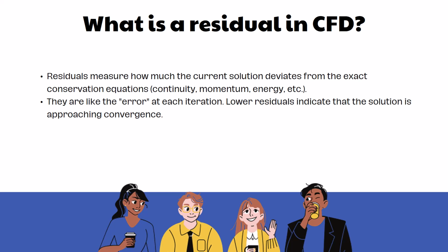So whenever your residuals are going very low, that means you are approaching your exact solutions, and which can be considered as an approach to the convergence.